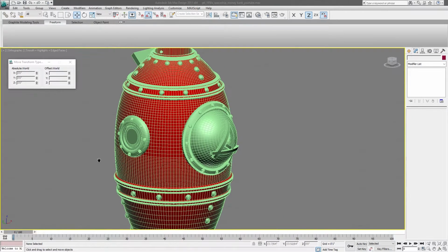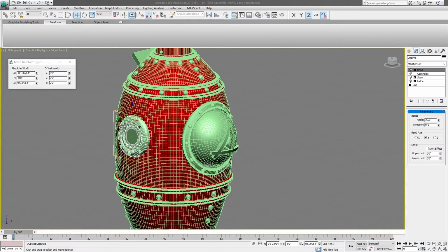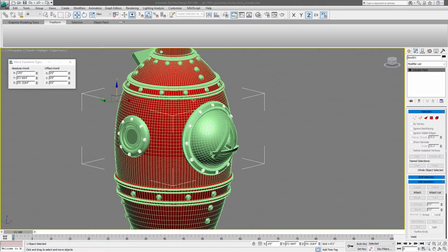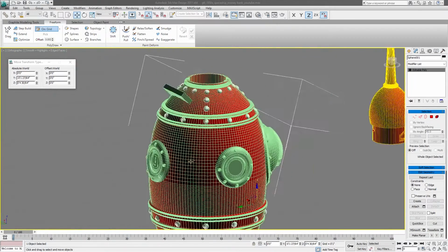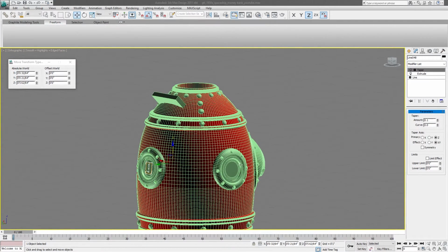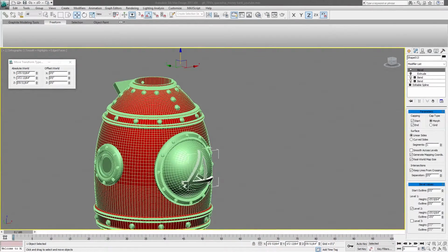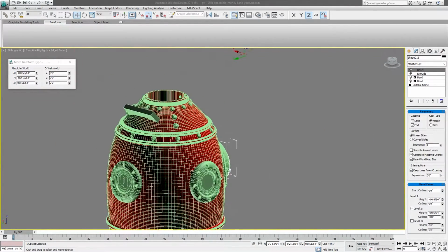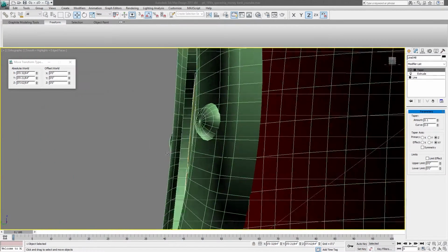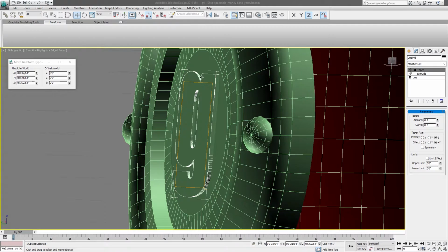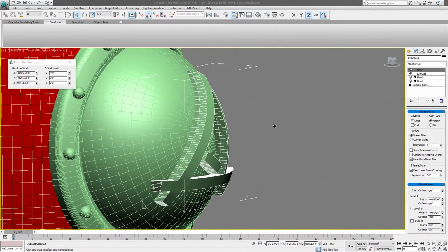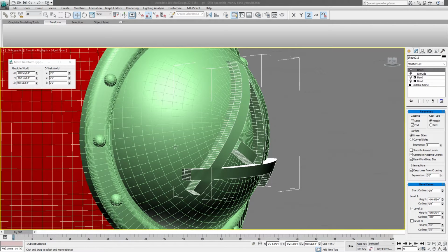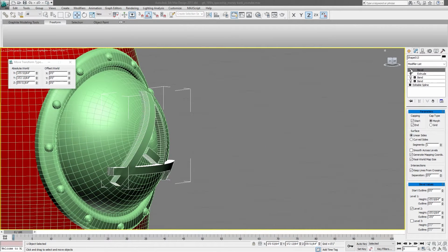So now we've gone over, quickly, how to make these portholes, and we talked about these spheres as well as these ones. These are the rivets. After creating these portholes, what we wanted to do was add our logo to the back of the model, and the other logo to the front. This one is a little bit offset from the surface. You can see it's stuck out of the actual porthole. This will be a union, so it'll bump out. And then the front one will be a subtraction Boolean, so it'll be embossed into the actual porthole.